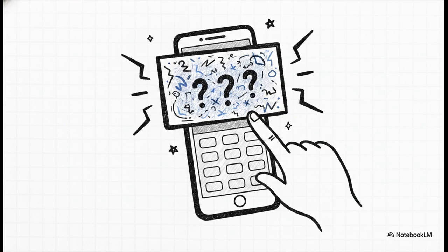But what if the software corruption is deeper than just a bad app? A fantastic, honestly kind of surprising insider trick is to open your dial pad and press *#06#. It feels like accessing a hidden developer menu. This brings up your phone's 15-digit International Mobile Equipment Identity, or IMEI number. If the resulting number looks totally garbled, has missing characters, or is just full of question marks, you instantly know you're dealing with a deep identity software corruption that requires specialized tools to rewrite.